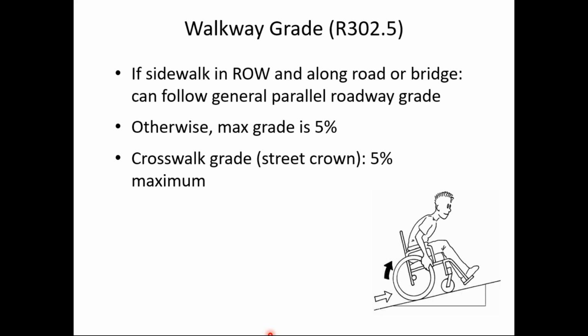Walkway grade. And here PROWAG and ADAAG that I mentioned earlier differ. In the public right-of-way, if the sidewalk is in the right-of-way and serves the road or street or bridge, it can follow the general parallel roadway grade, no matter how steep it is.